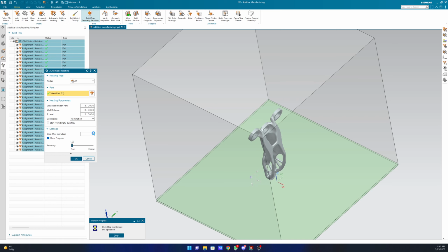I should have set it to 2, but okay. It will give better results if you give it more time. So it can fit more parts if you give it more time. So I'll suggest you to go with 10 or 15 minutes. So by then it will either tell you that this is the best I can do, or it will go till 15 minutes and give you the best, like it will fit the most parts in the same volume. Like you can set the time, like after 15 minutes, it automatically stops, right?